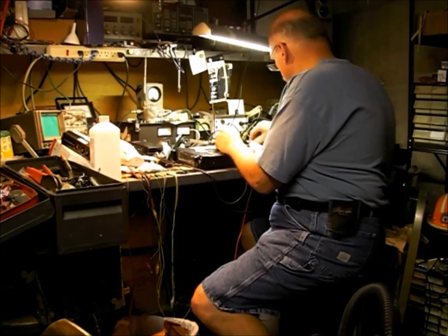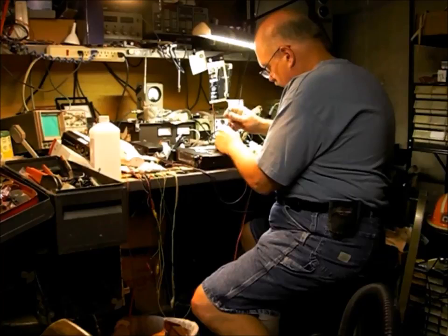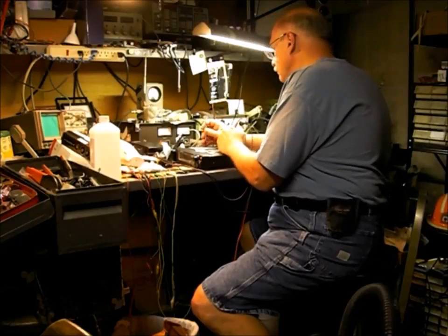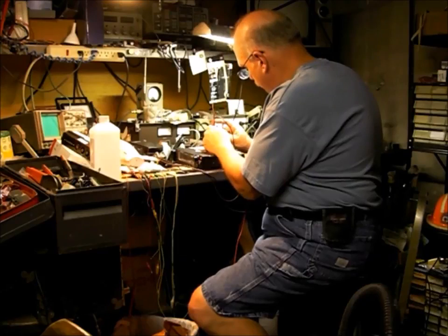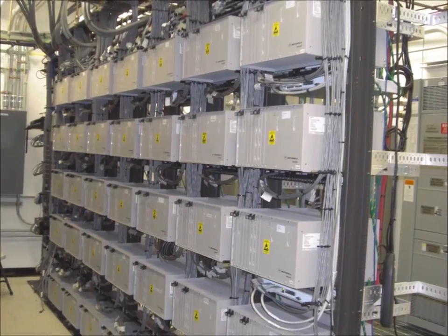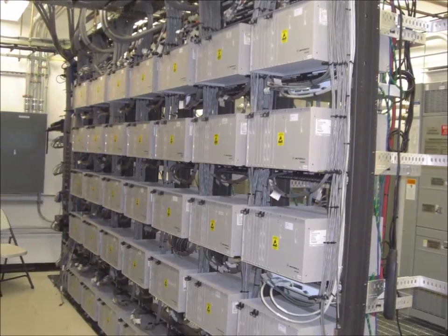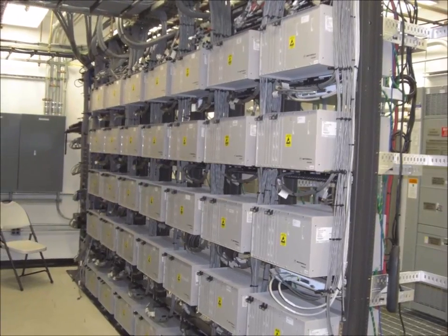The disadvantage is that there is higher maintenance. There are usually more sites, more equipment to maintain, and they are technically complex. The transmitter frequency must be highly stable, and this is usually done with a highly stable reference oscillator or through high-stability GPS receivers.